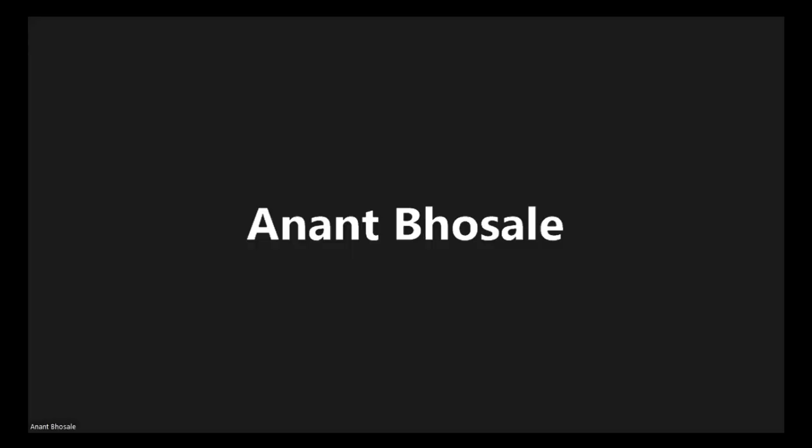Yeah, epoxy or vinyl, either one can be used for the flooring, for the walls also. So comparing epoxy and vinyl, what I find advantage with vinyl is we can do patchwork for maintenance. If an epoxy flooring or a wall layer cracks at the corners or anywhere, we have to redo the entire thing. So maintenance sometimes becomes costly that way. Whereas vinyl, it will be less. You can do only that much patch. So that is one of the advantages I find with vinyl.